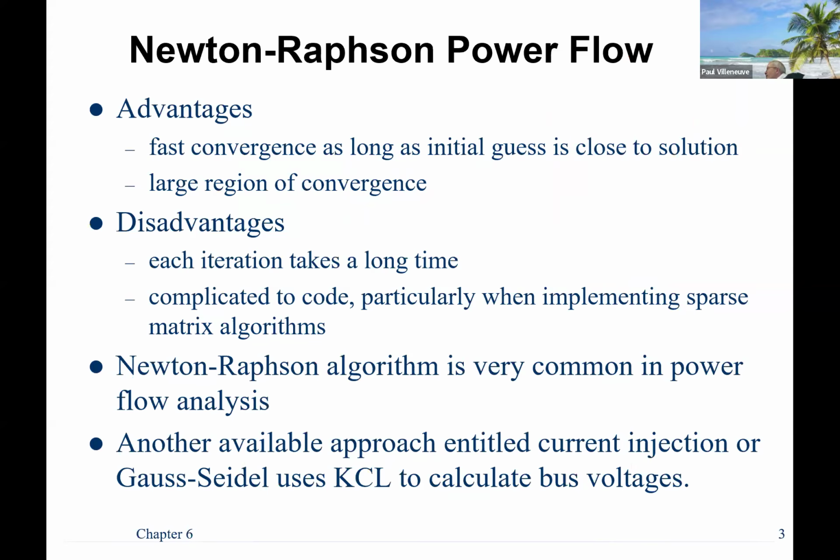So now that we know how to do it, what are the advantages? There are other methods to do load flow. One is called Gauss-Seidel, which if you can't get Newton-Raphson to converge, you can try Gauss-Seidel. I've never had to use Gauss-Seidel to get the convergence, but I will freely admit, I've only done maybe half a dozen to a dozen actual power systems analysis where we had to do a load flow. I do more of the protection side of things.